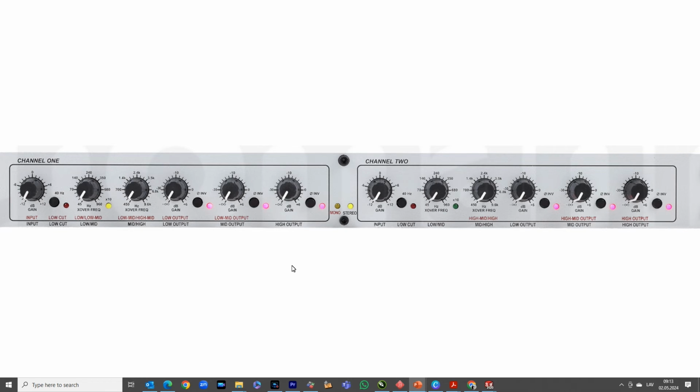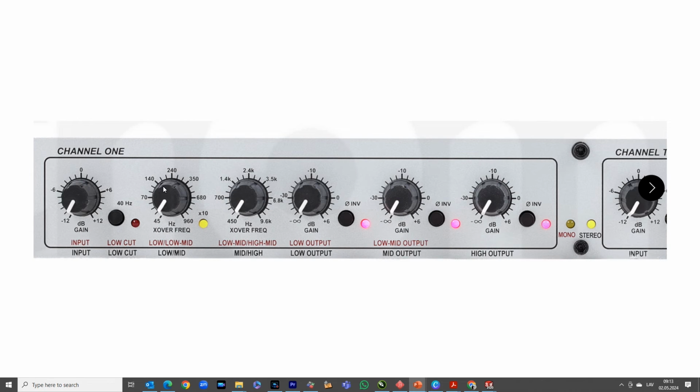Coming back to settings, let's take one channel, and the first thing you should do is set up one channel. Step 1, we set our lower crossover point between woofer and mid-range to 380. It's somewhere here. It's not that critical. Don't worry about that.